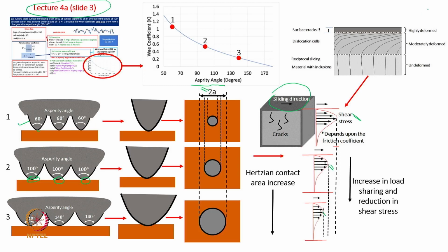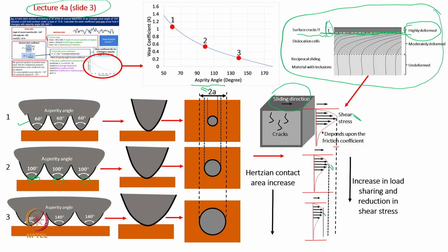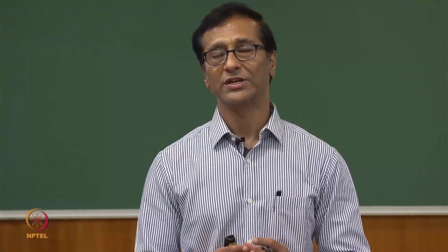Again I am taking this figure from my earlier slide. This figure showed that whenever there is loading, unloading and tangential load, the top layer will be highly deformed, and the strain is so high that it can initiate some sort of separation. There is a possibility of dislocation, or separation or delamination of this layer, which can be explained using fatigue phenomena also. If there is some sort of subsurface crack, this sublayer, this thickness, can be removed, can be delaminated from the surface.